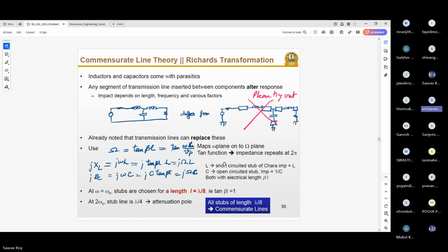And the main part, what you derived for this, the omega is tan beta L. You have used the normal waveguide parameters and finally arrived at this expression, right? No, actually I have not arrived at it. The Richards transformation has arrived at this. The basics of this we can find in Pozar. Everything I am following, you can follow in Pozar. Yes, I'll check once. This is the backbone. This is what Richards proved; rather, I should not say said.